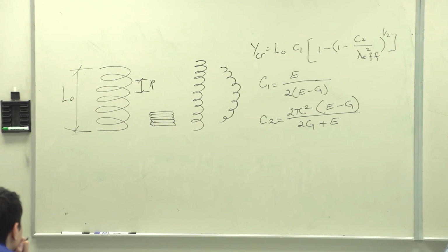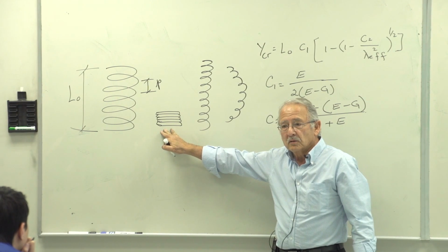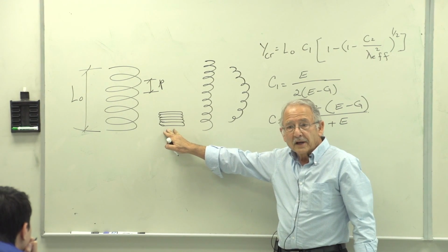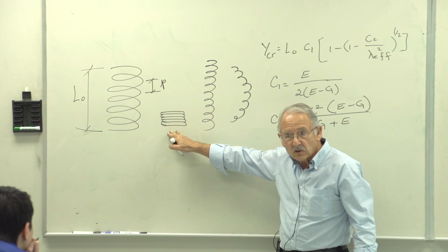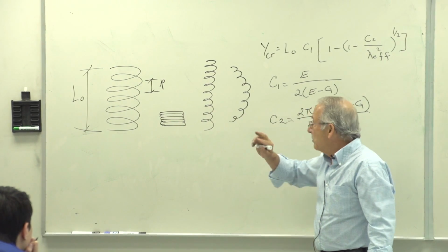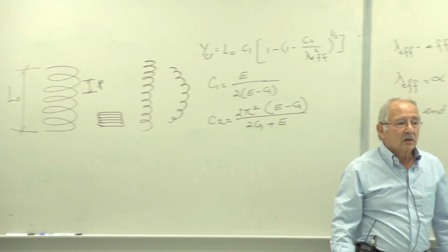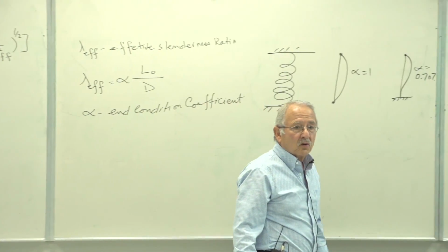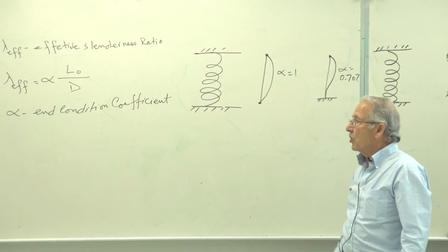We would like to design springs so that you can compress the spring to its solid height and it will not buckle. Therefore, we must make sure that such deflection does not exist, that there is no way we can put that deflection on the member.